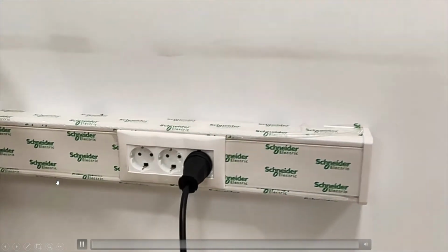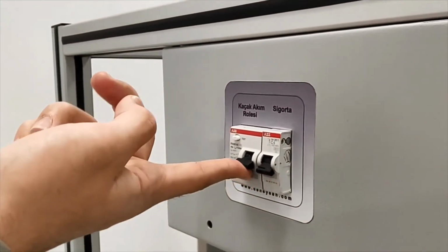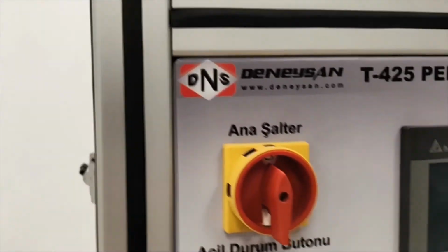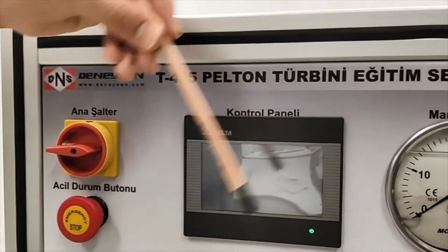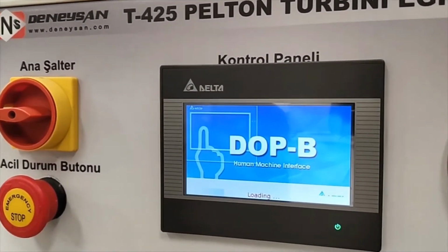First of all, we make sure of the electrical connection, and after that we open the leakage current relay and the fuse. The left one is the leakage current relay and the right one is the fuse, and we turn on the main switch, and the electric power comes to the control panel and the control panel turns on.